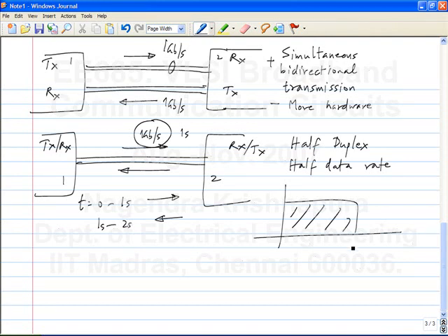Now, if I have to have, let's say 1 gigabit per second data and separate them in frequency, I have to put it somewhere well above 1 gigahertz, right? This can be one way and this can be the other way. But if I do this, now this part is at a very high frequency, which I am assuming is not supported by this transmission line. Okay. It is attenuated severely. So I can't translate it to a higher frequency. So this is broadband data. You understand that, right? So if you have to translate it to a higher frequency, you have to translate it to very high frequencies. So can you just throw caution to the wind and transmit both ways? Have you seen a system like that?